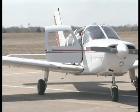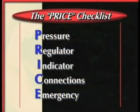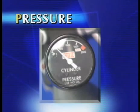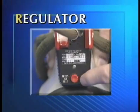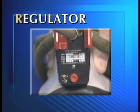Prior to every flight, you should perform the PRICE check. The PRICE is a checklist that helps pilots and crew members inspect oxygen equipment. Pressure. Ensure that there is enough oxygen pressure and quantity to complete the flight. Regulator. Inspect the oxygen regulator for proper function.